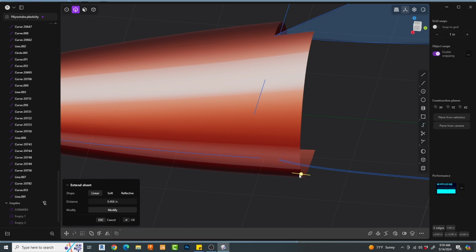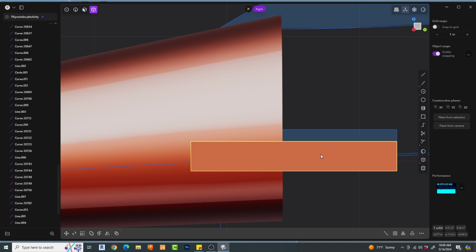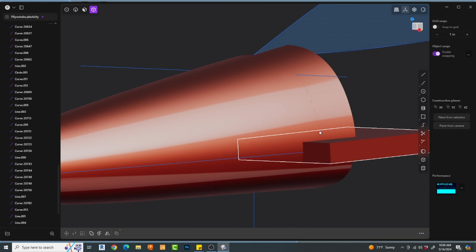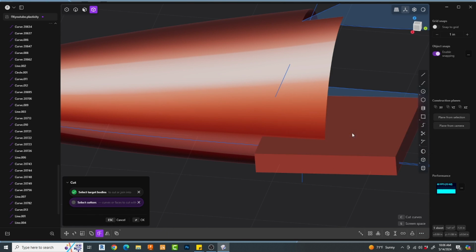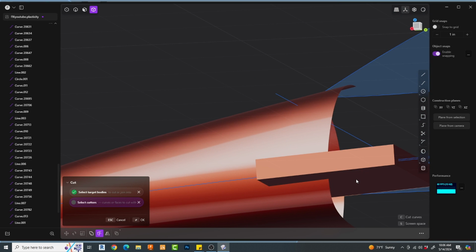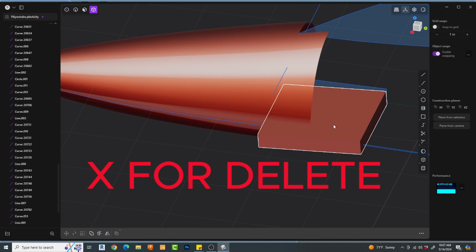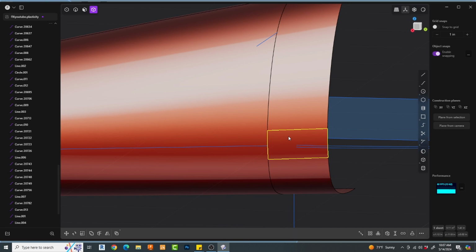I'm going to extend my edge out here just a little bit temporarily, and then I create a cube where I'm going to put it exactly where I want it, and then use a Boolean operation. Oh, sorry, no, I split the nose cone, and now I'm just going to trim by the faces of those so that I have one section of this that works the way I want it, and then I'm going to begin to use the raise degree command on that one surface.